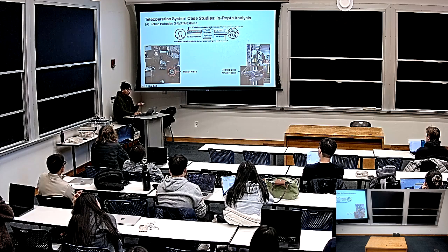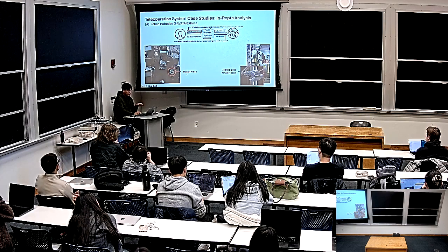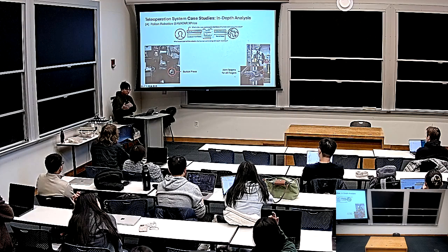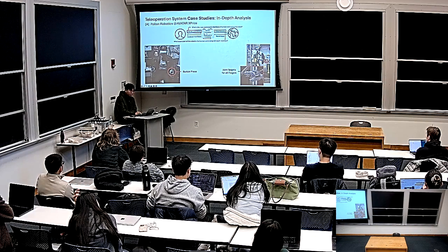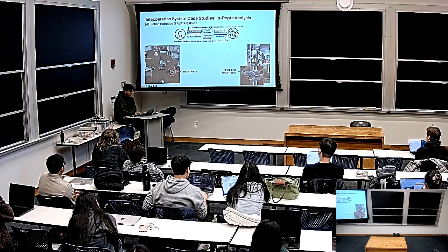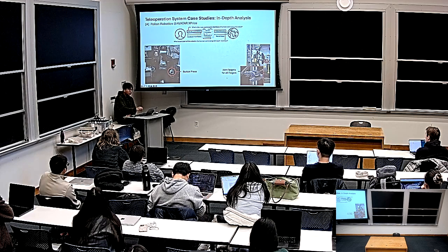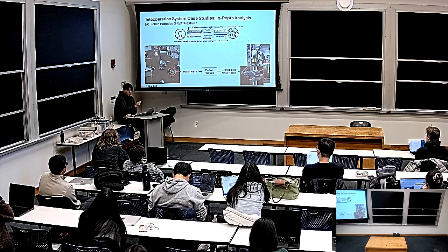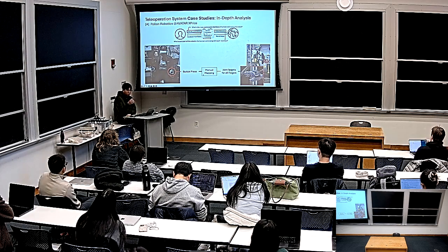If you see the video, the operator is clicking different buttons from time to time. And this button press has to be mapped to different styles of joint targets for, if you can see over here, the 3 fingers. So it's much higher degrees of freedom than a single button press. We should somehow map these button presses into those different types of grabs that we humans do. And that's been done by manual mapping in this kind of teleoperation scenario. So they have different buttons like opening, closing, or pinching, and they are mapping those kinds of hand movements into different buttons.